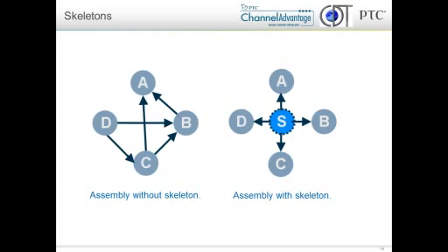So note the following 2 diagrams. Yes, an assembly with only 4 components may not fully benefit from a skeleton, but imagine this had 400 or 4,000 or 40,000 components in it. I think it's pretty easy to see how a skeleton could decrease your regeneration times by simplifying the way components are constrained into the assembly. Creo Parametric no longer has to validate the mate between parts D and C, and also C and B, and D and B, and A, and it's a good thing that Creo's smart, because that kind of thing confuses me.